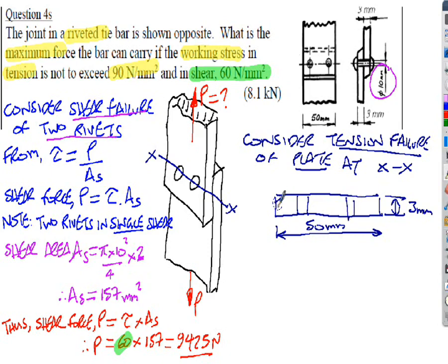So if you imagine I've hacksawed through the plate, through the holes where the rivets are, that's the kind of section I would see. Imagine as my hacksaw, I would see that kind of section there, and this would be the rivets. And we know the diameter of the rivets in this case is 10 millimeters, given in the question.